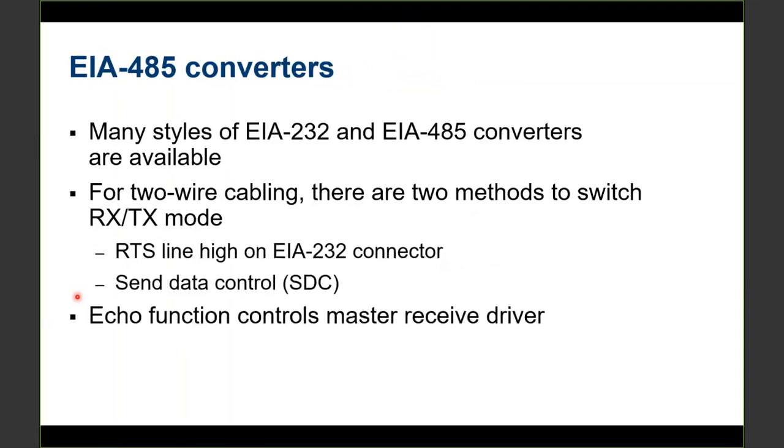Okay, so as far as converters go, we have the SEL 2886 that converts 232 to 485 communication. There are also third-party devices out there for that. But for two-wire cabling, it's important to know, for four-wire, it's not a big deal. The full duplex translates real nicely to 232 communications. But for two-wire, there's basically two modes.